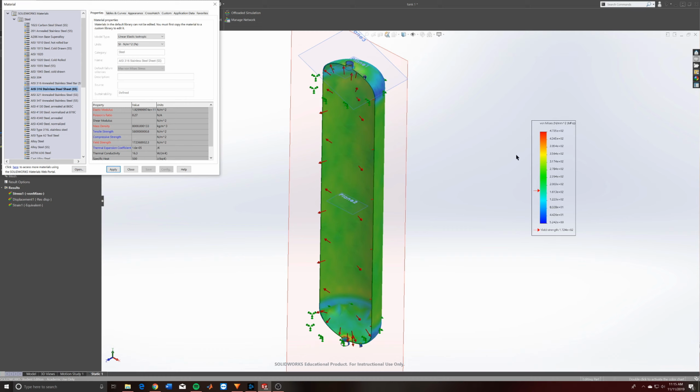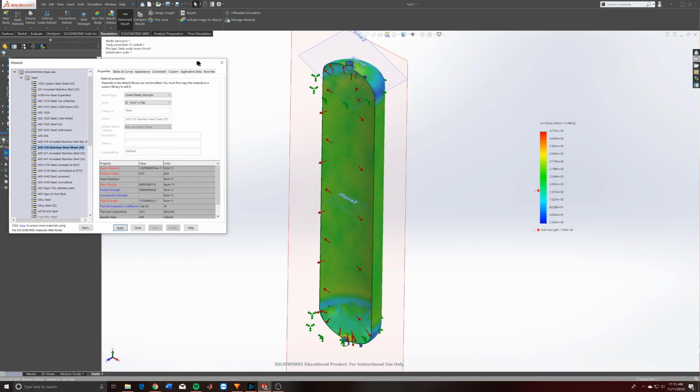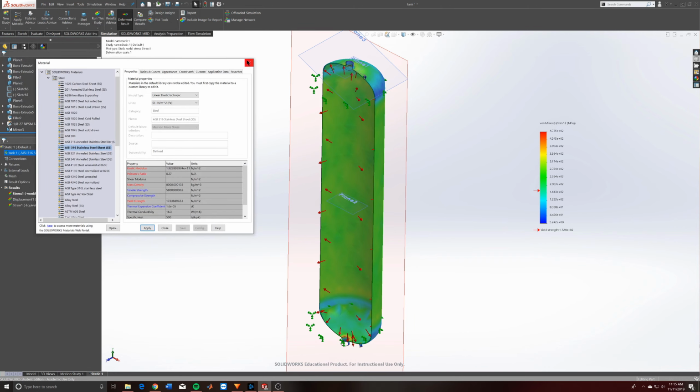But essentially, since we want to make these tanks as light as possible, we care if they deform and things like that, but these are most likely going to be minimal use tanks. Like, these are going to be made for flight, and they're going to be filled up maybe once or twice and launched, and that's it. So we're going to have to really determine a minimum thickness that's acceptable, keeping in mind the ultimate tensile strength versus just the yield stress of the material.